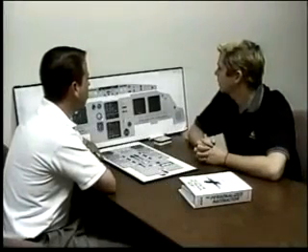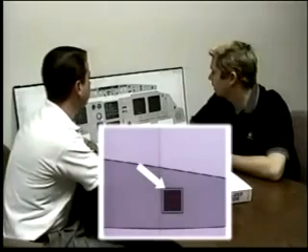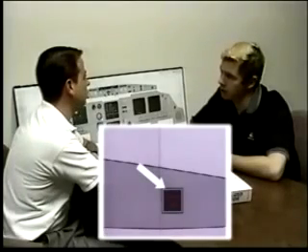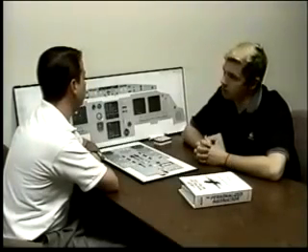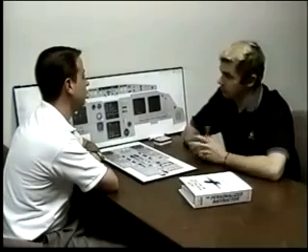Describe to me the parameters in which you get an autoland light. Okay, autoland light only occurs during an autoland approach, and it's armed at 200 feet. There are three things that are really going to illuminate the autoland light. From 200 feet all the way to the ground and rollout, if I lose both autopilots, not one, but both autopilots, the autoland light's going to come on.